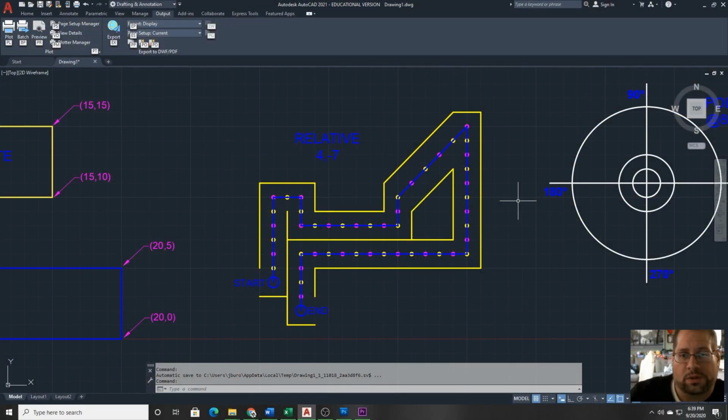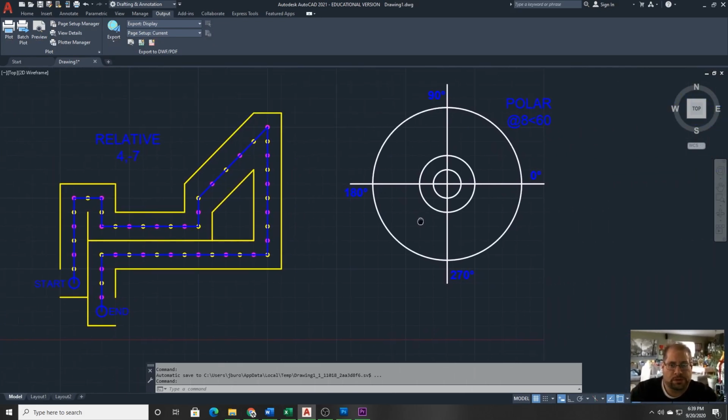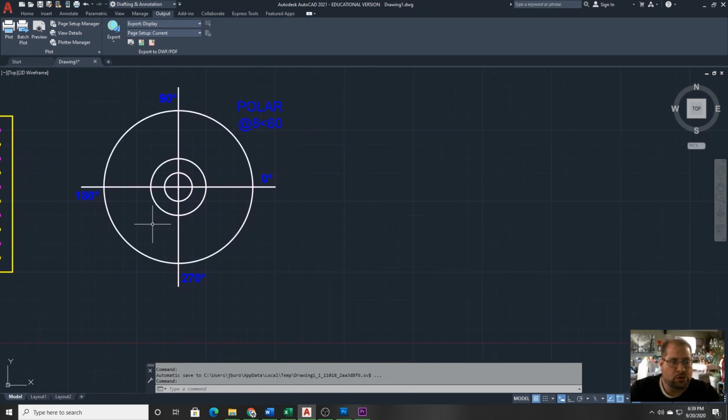Okay, we're going to pick up with the coordinate systems right now with the final coordinate system, the polar coordinate system. With the polar coordinate system, you are going to be drawing on the screen also relative to your current position, but now instead of specifying a direction and a distance with the x and y axis, we're going to be using a degree for direction from 0 to 360 and a distance value that can be described as like the magnitude of a vector. And I'll show you what I mean by that.